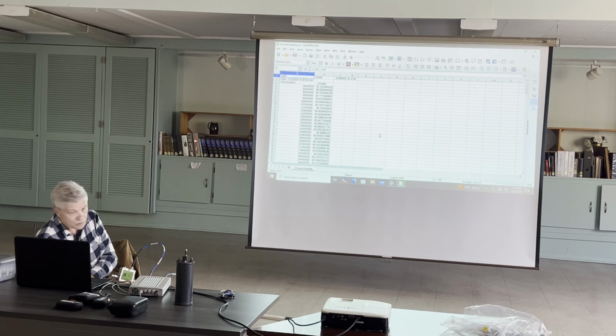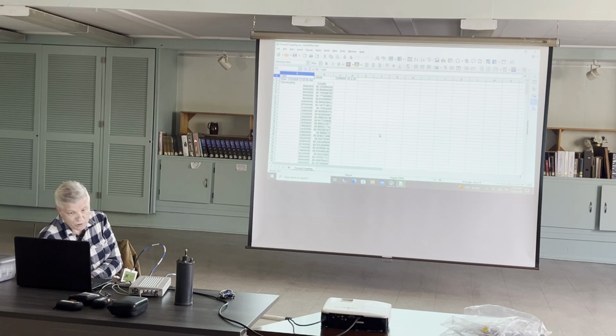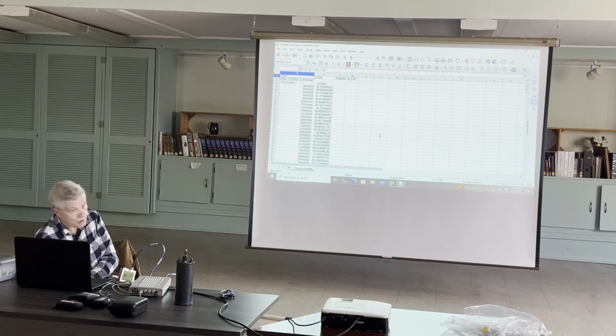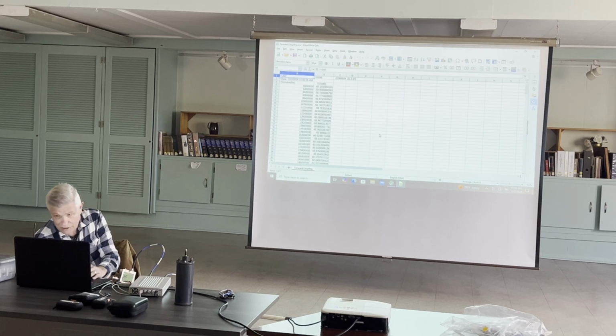Because if we don't know that, we can't precisely measure what the power is. We need a resolution of about 0.05 dB. That's 1%. That would be a 1% error. So if you don't know the coupling out to the second place to the right of the decimal point with any degree of certainty, then your power measurement won't be very accurate. So that's how we display it.